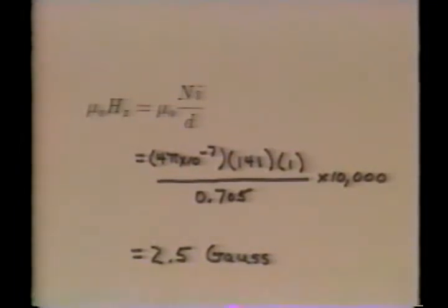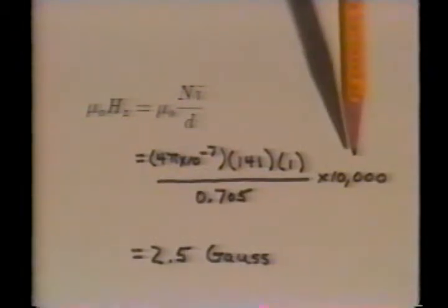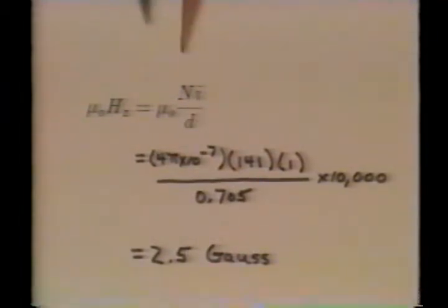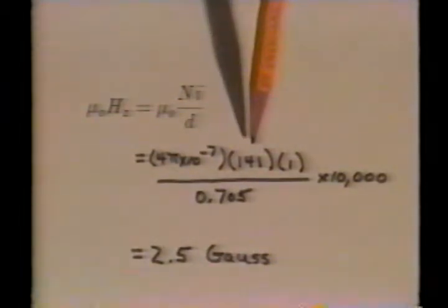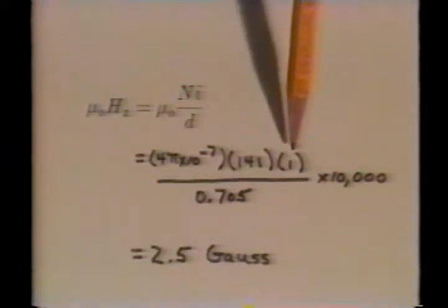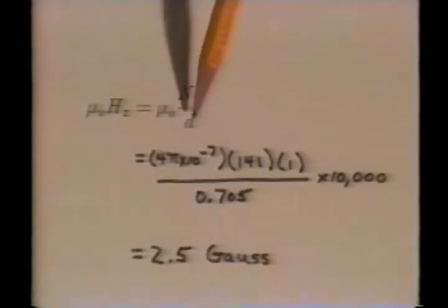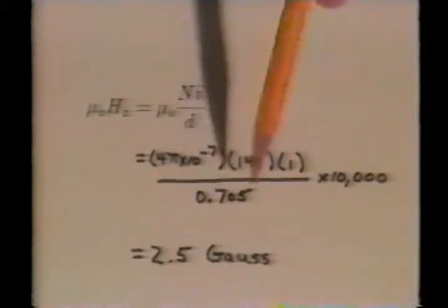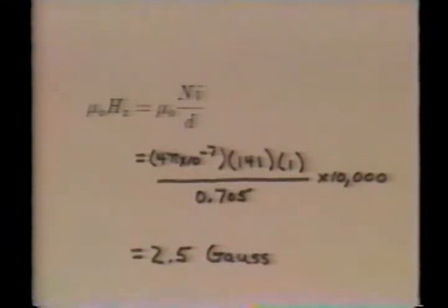Let's measure the magnetic field well inside the solenoid. We measure about 2.3 Gauss just inside the winding, as compared to the prediction of 2.5 Gauss. Let's see what the tangential flux density is just outside at the same axial location. Just outside, the flux density falls by more than a factor of 10 to 0.15 Gauss.